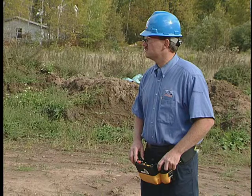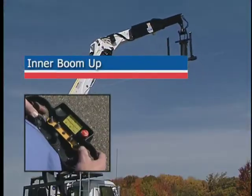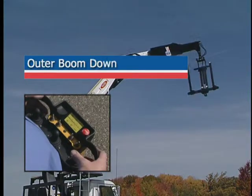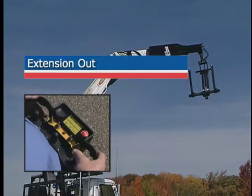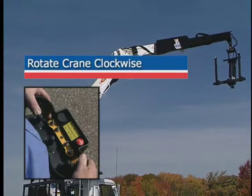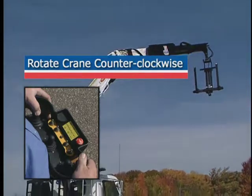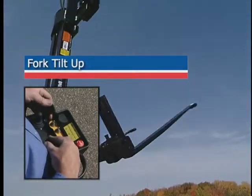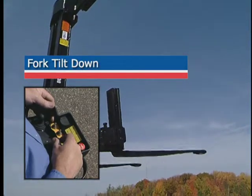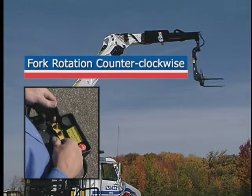The 2 joysticks left and right perform these functions: inner boom up, inner boom down, outer boom up, outer boom down, extension out, extension in, rotate crane clockwise, rotate crane counterclockwise, fork tilt up to close the fork, fork tilt down to open the fork, fork rotation clockwise, fork rotation counterclockwise.